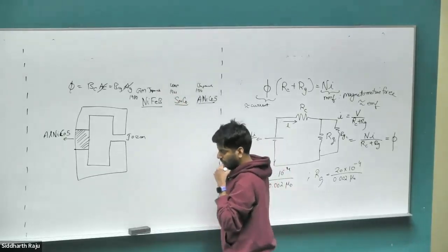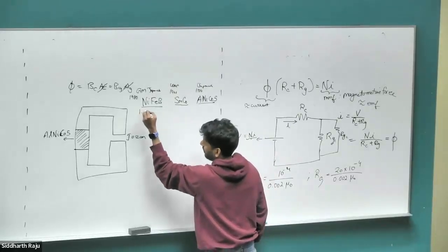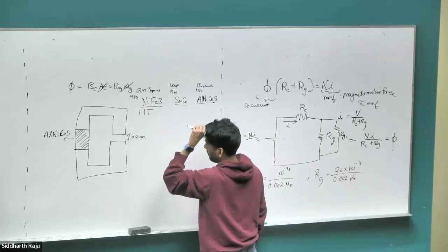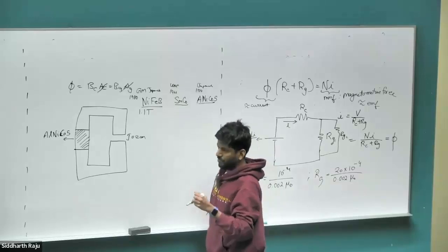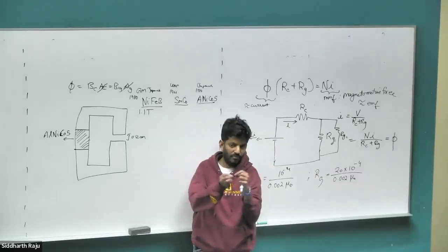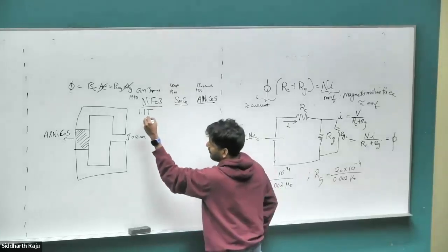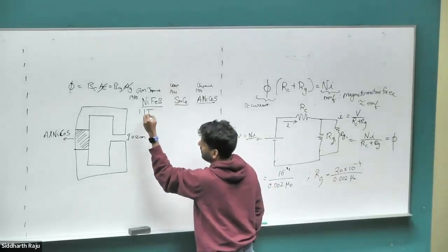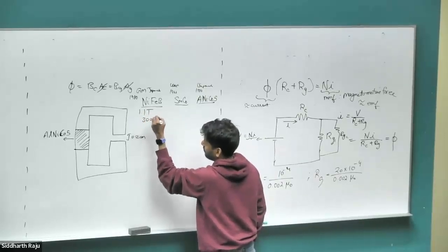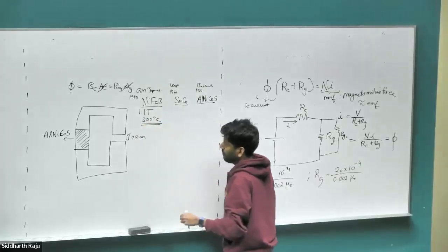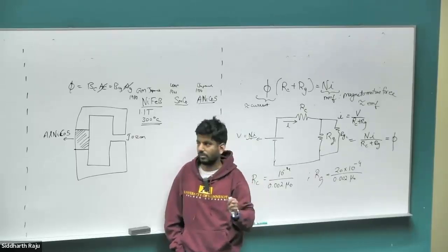Typically in our motors, we would be using neodymium magnets because they have very high retentivity and they have large coercivity as well. But one of the biggest problems with neodymium is that they are very brittle. Those of you who have played with neodymium, if you leave two neodymiums, they'll hit one another and break right away. They're extremely brittle magnets. The other bigger problem is they get demagnetized quite easily with temperature. Typically around 300 degrees C, that's the Curie temperature, which is the temperature at which all the domains get randomly aligned and they lose their magnetic field instantaneously.